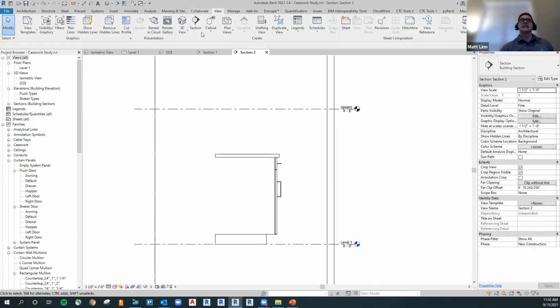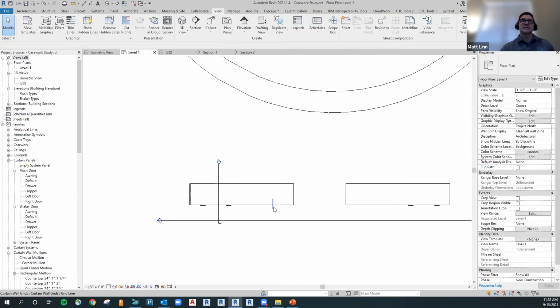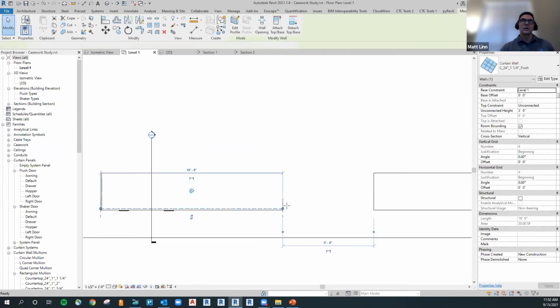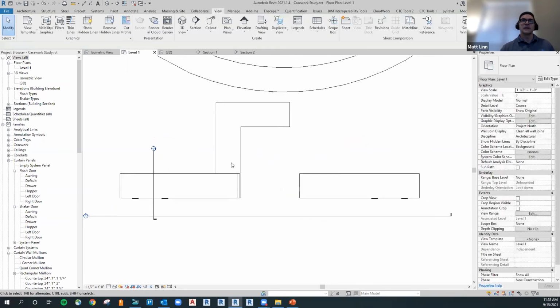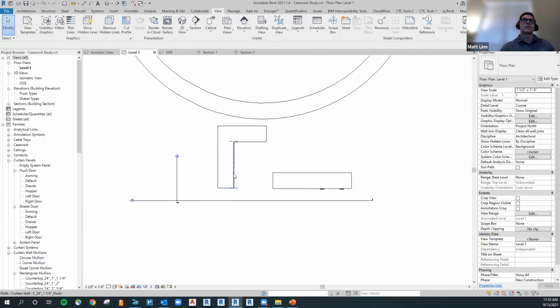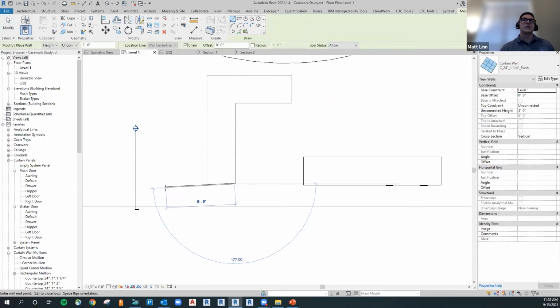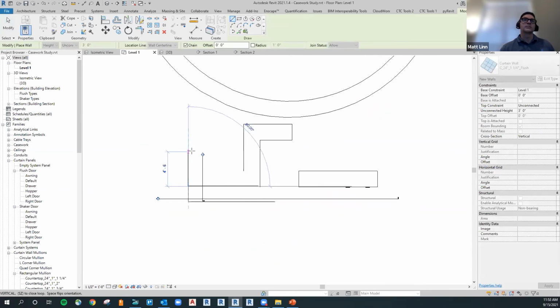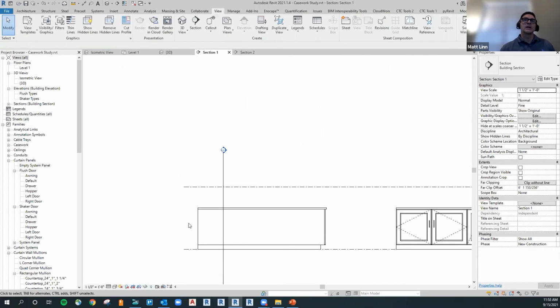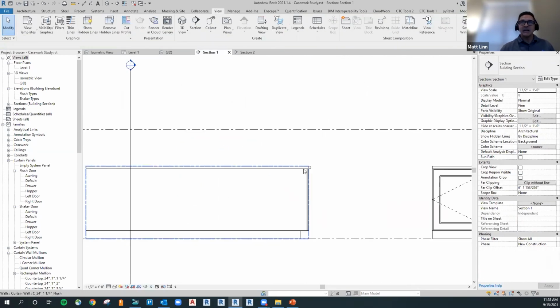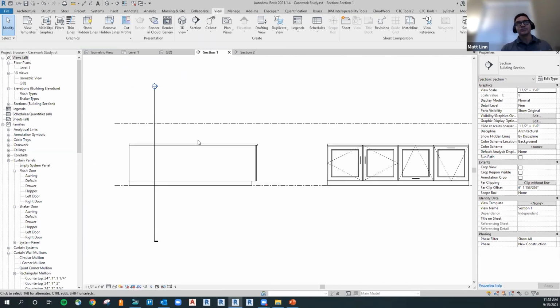The downside to that is if you're looking at, let's say this curtain wall continues like this, or this casework, I should say, and then if this came around, we would end up seeing that here in elevation, because as you know, symbolic lines you can see whenever you're in a perpendicular view.